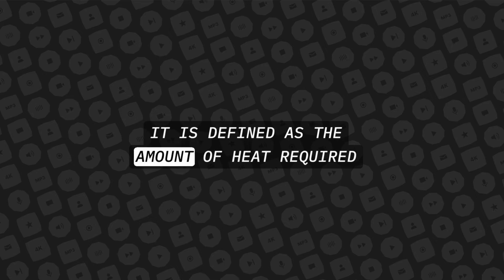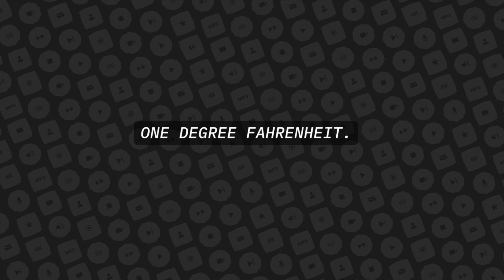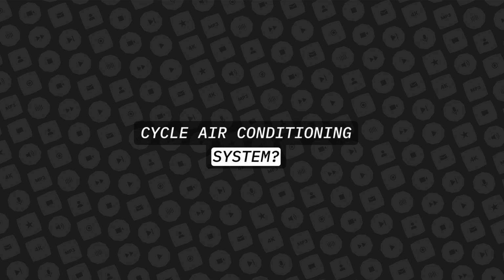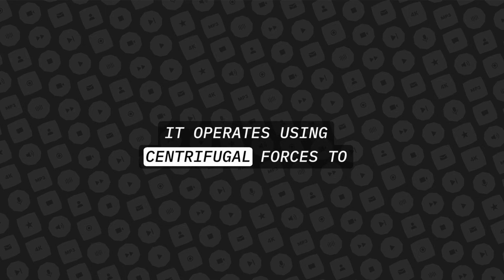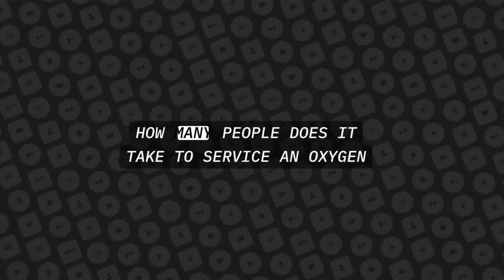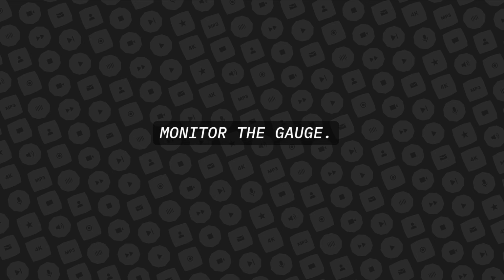It is defined as the amount of heat required to raise the temperature of 1 pound of water by 1 degree Fahrenheit. How does a water separator work in an air cycle air conditioning system? It operates using centrifugal forces to spin the water out of the air. How many people does it take to service an oxygen system? 2. 1 to apply pressure and 1 to monitor the gauge.